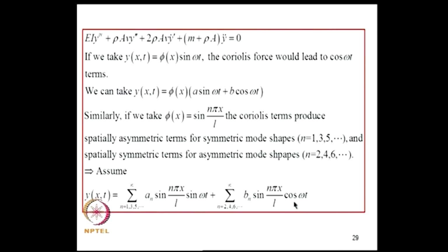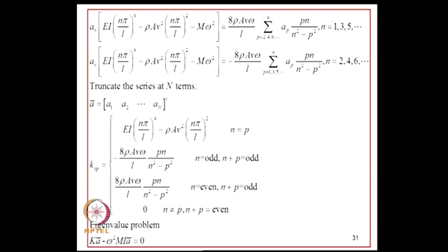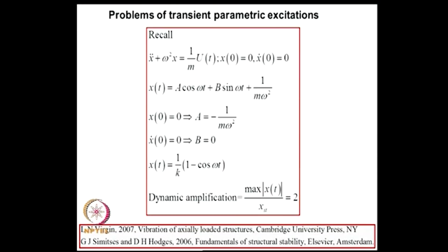We will discretize, deal with a generalized eigenvalue problem and examine the relationship between complex valued natural frequencies, mode shapes and the flow velocity, and infer without introducing any ad hoc assumptions or selecting functions which do not satisfy boundary conditions and so on and so forth. We can examine what the finite element model teaches us. So, this is left as an exercise.